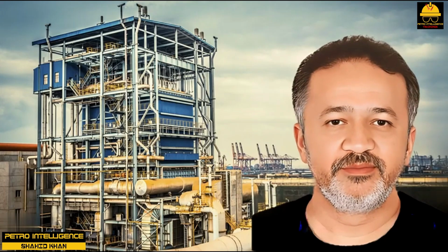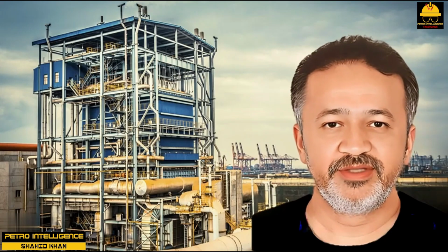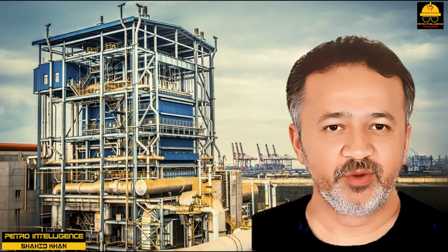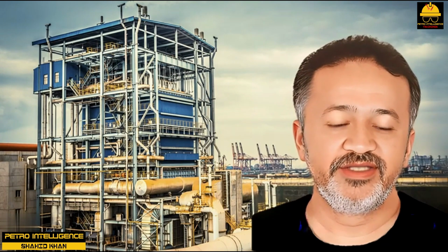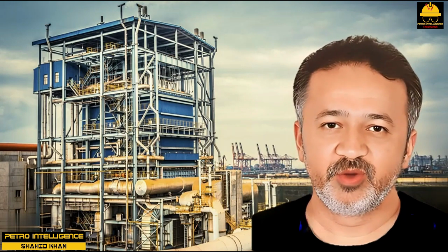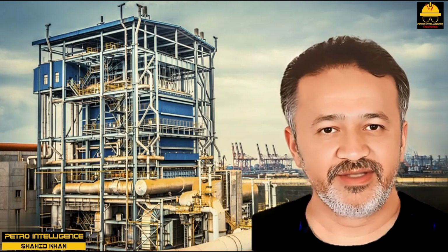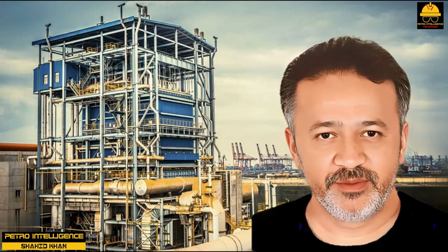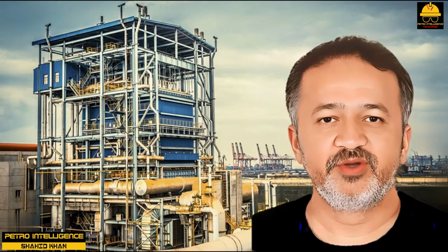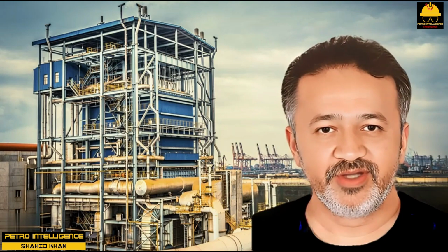Sintered metal tubes. The development of sintered metal tubes dates from the 1970s. A rough coating is applied to the exterior of the smooth new tubes. The hottest fluid is on the tube side. Boiling is intended to take place on the shell side or exterior of the tubes. This is only useful in flux-limited situations when boiling relatively pure components and when heat transfer rates exceed 10,000 BTU per hour per square feet. In such circumstances, the sintered metal tubes act like boiling stones by the way in which they provide sites to initiate nucleate boiling and thereby overcome flux limitations.